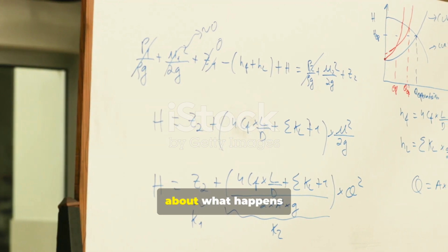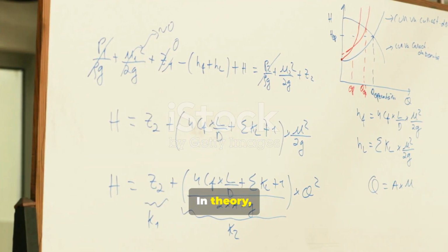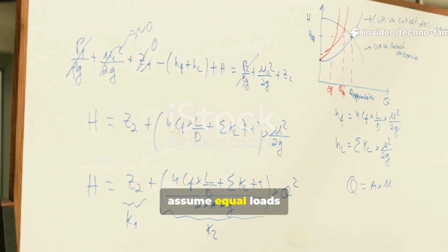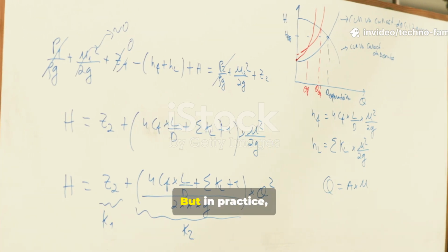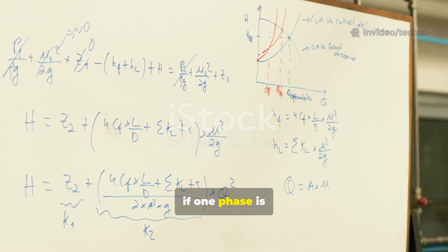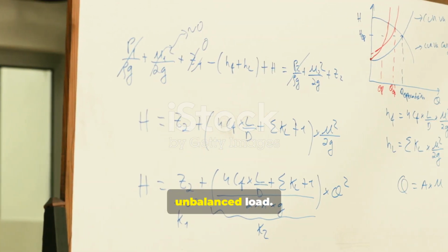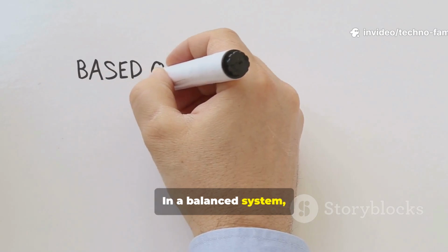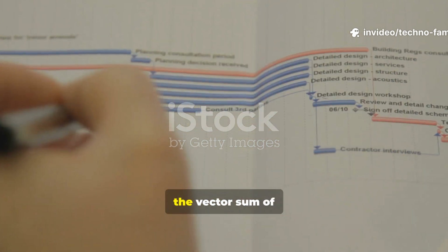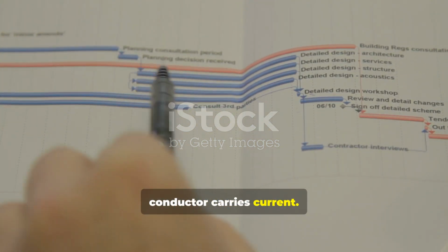Now let's talk about what happens when the system is not perfectly balanced. In theory, three-phase systems assume equal loads on each phase. But in practice, loads may differ. For example, if one phase is supplying more single-phase equipment than others. This is called an unbalanced load. In a balanced system, the three currents sum to 0 and no current flows in the neutral. But in an unbalanced system, the vector sum of currents is not 0, so the neutral conductor carries current.